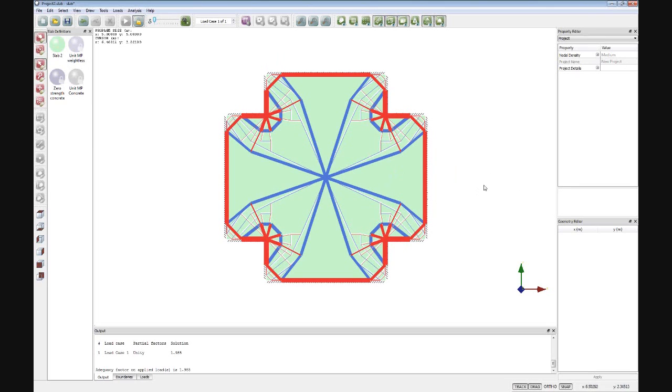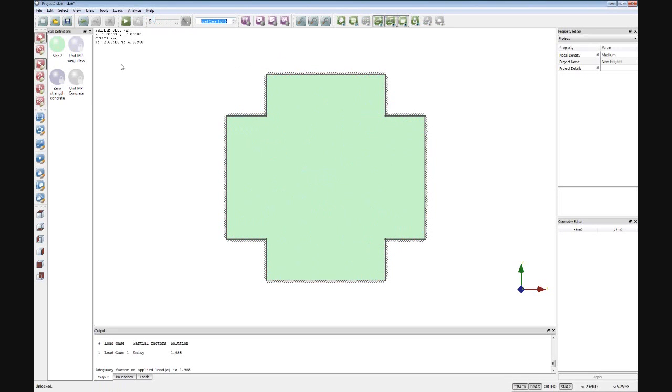The last way, so I want to very quickly just explain how you can get a problem into the software, is actually using a DXF file. So perhaps you've got a drawing of a problem that you've been provided with. You can very easily use that to create a geometry and then import that into the software in order to create what would be a more complex problem.